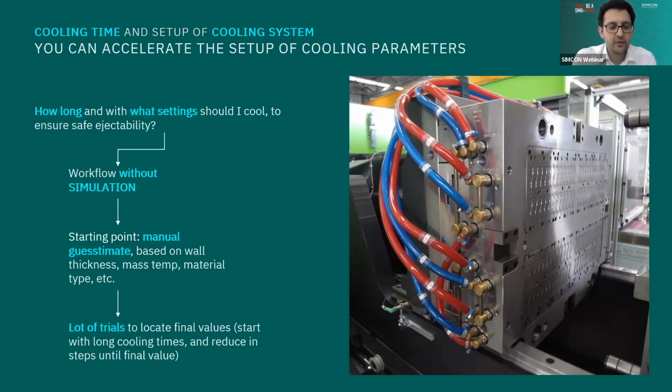And then do a lot of trials to locate final values, where you reduce the cooling times until the final value is reached. This also takes into account that you hope, basically, that the mold is well built and the cooling inside the mold is uniform.